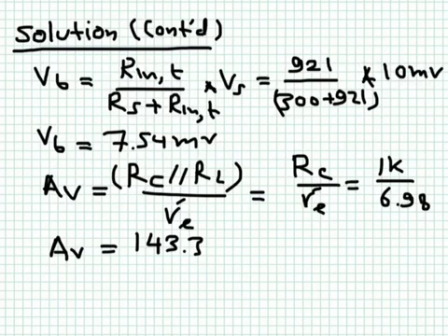Now, what is the definition of the gain? We already derived the expression. If you know that this is a common emitter amplifier and you are sure, you go ahead and use this expression. I used it here because I derived it earlier. And we agreed that the gain here is RC in parallel with RL over RE dash. There is no RL here. RL is infinity. RC in parallel with infinity is equal to RC.